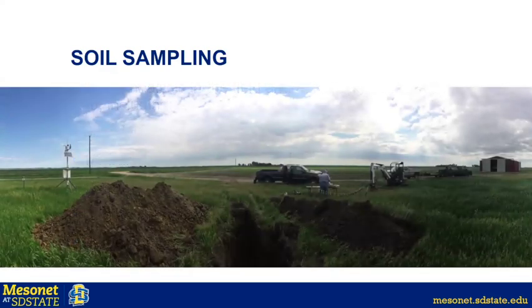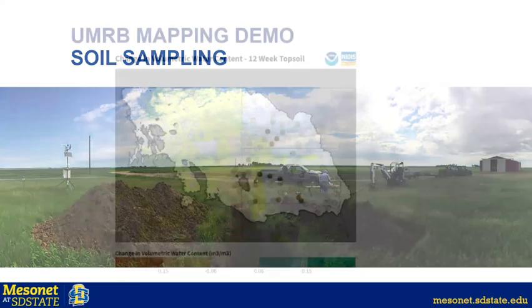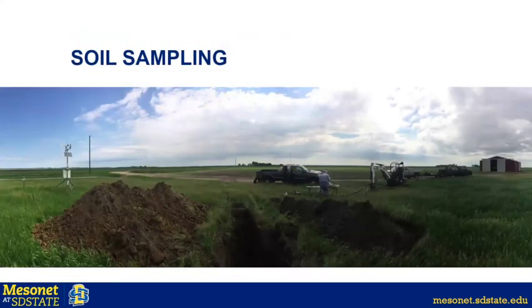This is an example of soil sampling done at a station before it was upgraded. I think this one was 80 inches, but typically 60 inches is the modern one. You can see there how they've got bags strung out for bulk density measurements, that kind of thing. So they do some of the work in the field and then they send the rest to the lab. A subset of the soil metadata will be available alongside the data. The rest of the PEDON report will be available through NRCS, for people that want to get into every bit of it.